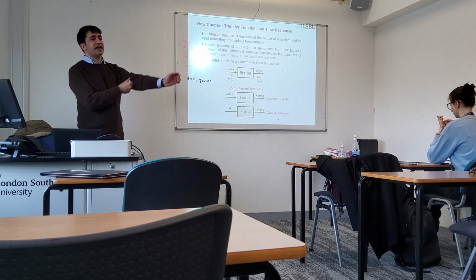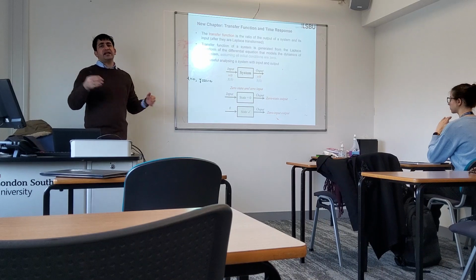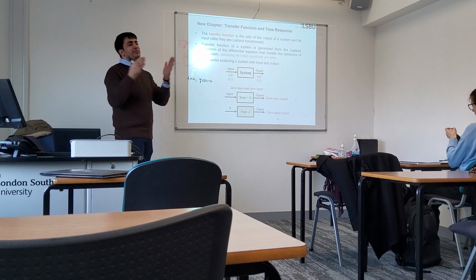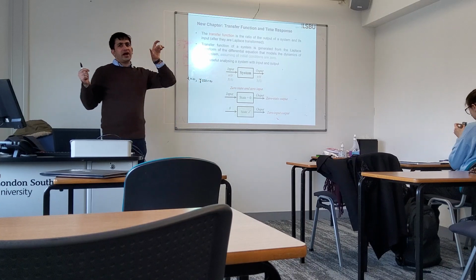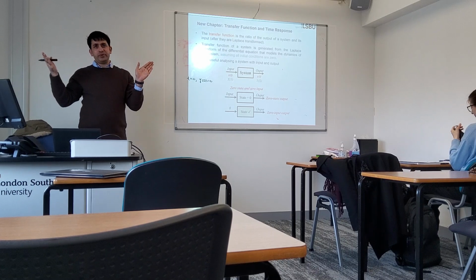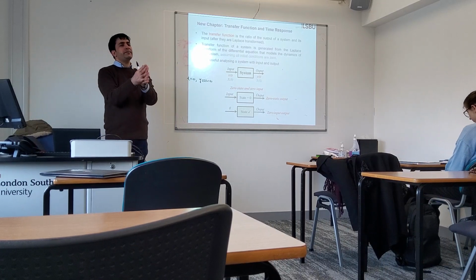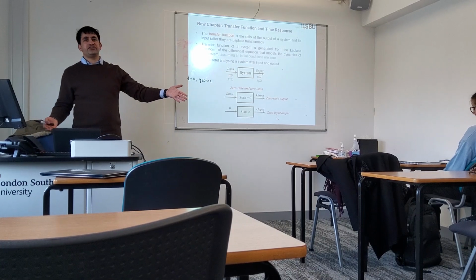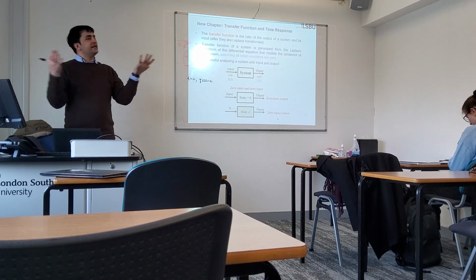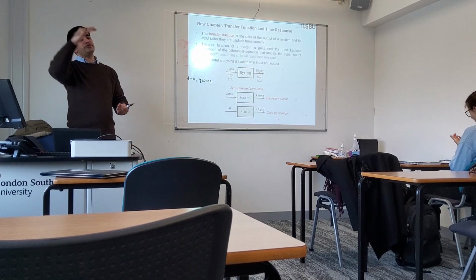And for any system, like I said, if, for example, you consider a battery was discharged and you apply input, and in the second case you consider that the battery was at some charge and you are applying input. If I split them separately, I can find a response for the system when there was no initial state and only the input, and then I can also find a response where there is no input and only state. If I combine both of them, I will get the total response. The first was under zero state, only input; the second was only state and no input; and combined it tells me that when you applied input, there was an initial state, so instead of starting from 0, it was starting from a certain point.